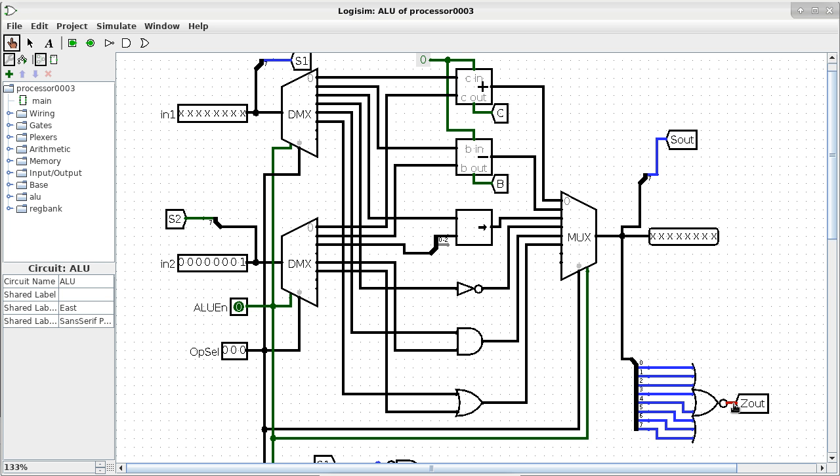We take a splitter, split all 8 bits into individual wires, okay, individual bits. Get them all through a NOR gate. Okay, this is a negated OR gate. So if at least one of these is a 1, then the OR is going to be a 1. But since this is a NOR, the NOR becomes a 0. So the only time the NOR gate will output a 1 is when all inputs are zeros. So this is how we detect whether the result of an operation is 0 or not. Are we good?